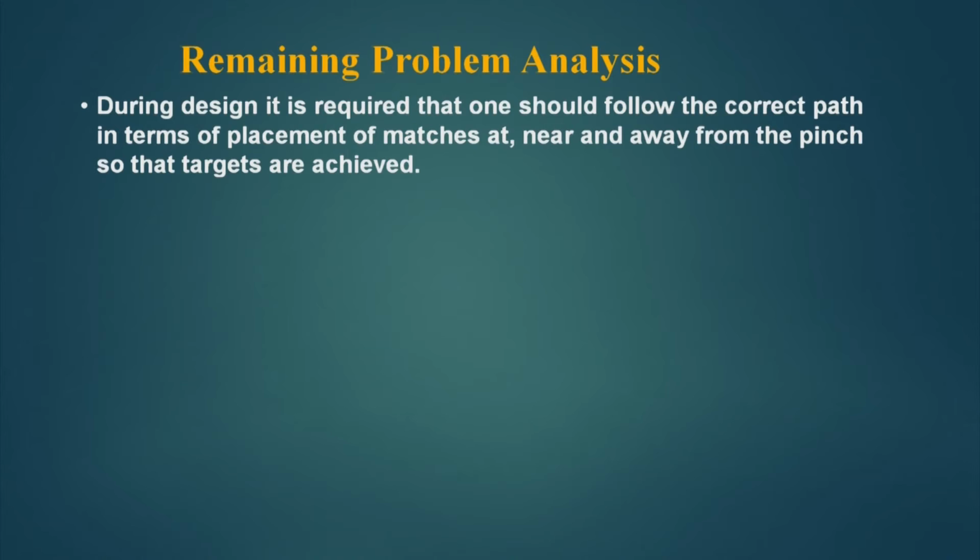Now, let us see the third rule, which is called remaining problem analysis. Basically, it is not a rule, it is a method to steer the design in proper direction. During design, it is required that one should follow the correct path in terms of placement of matches at, near and away from the pinch, so that targets are achieved.